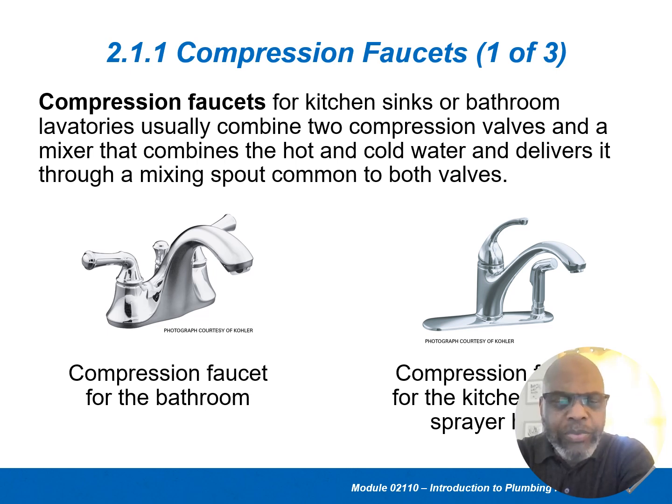The problem is when that rubber washer wears out, that's when the sink starts to drip. And the longer you let it go, the more it will drip until it's a steady stream. After years of wear, the metal seat can wear out, and sometimes that needs to be replaced. Having the right tools to remove that seat and replace that washer becomes important.